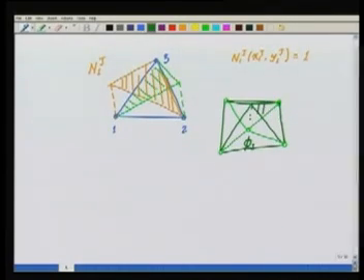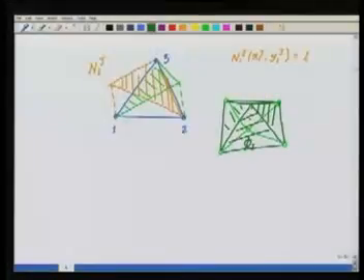It is one at the node with respect to which it is defined, and it is piecewise linear in each of the elements which share that node. Remember again that in the two-dimensional case, a node may be shared by many more than two elements. In this figure that I have drawn, there are 4 elements sharing a node. So this basis function has to be defined with respect to all the elements which share that particular node.